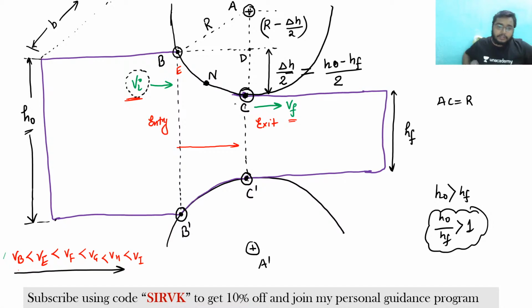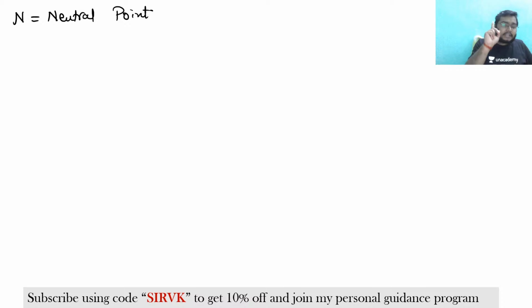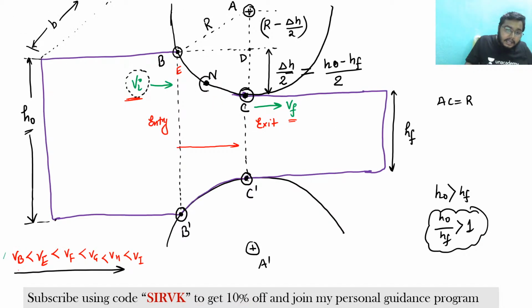We have also seen that there would be a velocity of the roller, that is VR. So there would be some point, which is N. At this point N, the velocity of the workpiece would be equal to the velocity of the roller, and this is known as the neutral point.